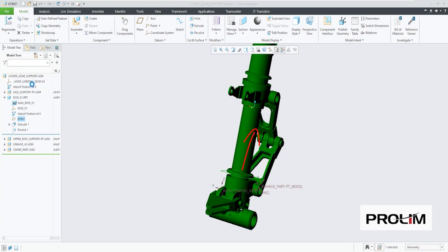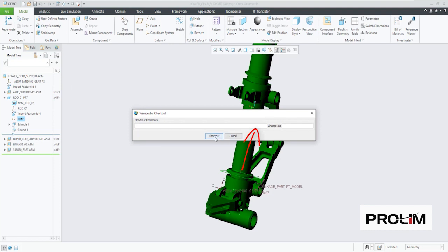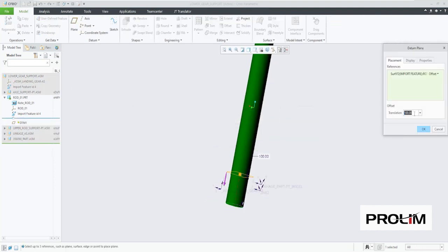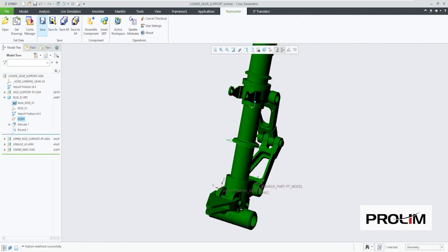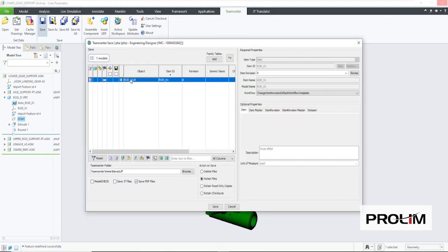What happens when the Creo design is changed in its authoring tool and saved back to Teamcenter? Remember that the Creo design is directly reused by SOLIDWORKS, allowing the SOLIDWORKS parent assembly to maintain any constraints that were made against the Creo models. In this case we're simply moving the feature that was used in the SOLIDWORKS mate.